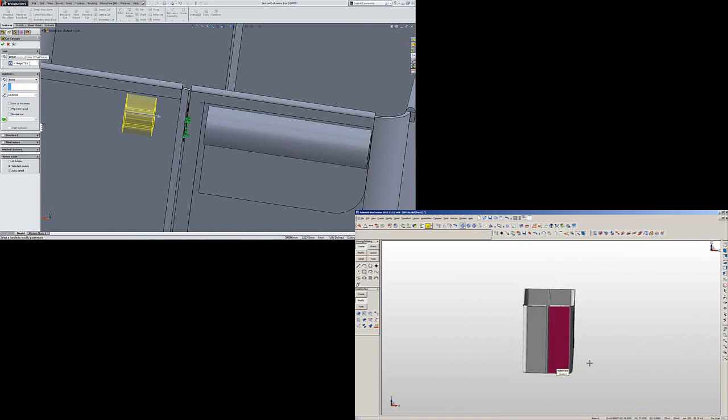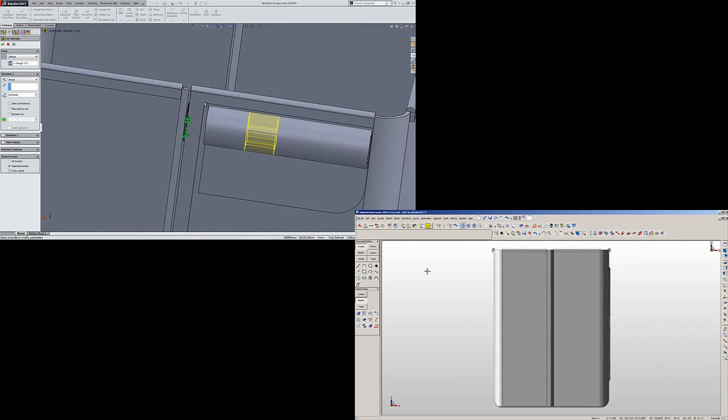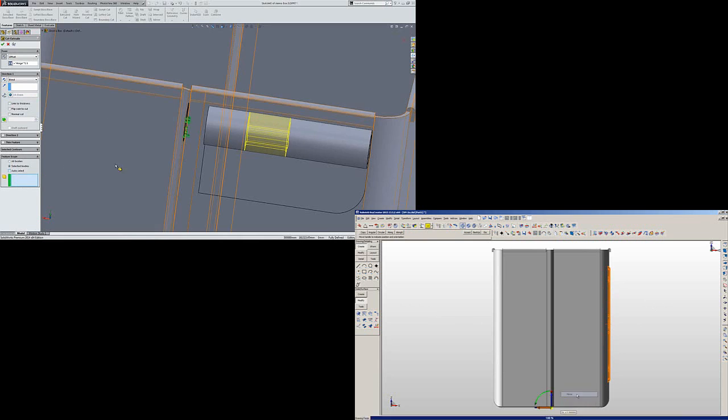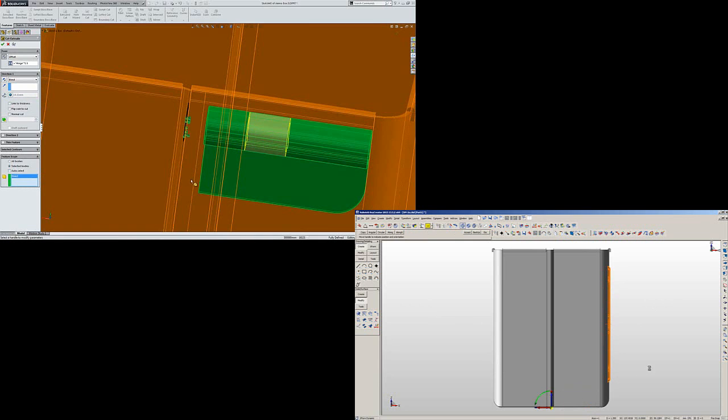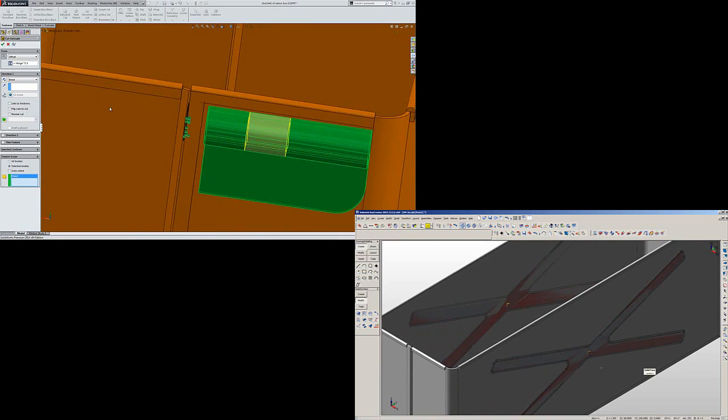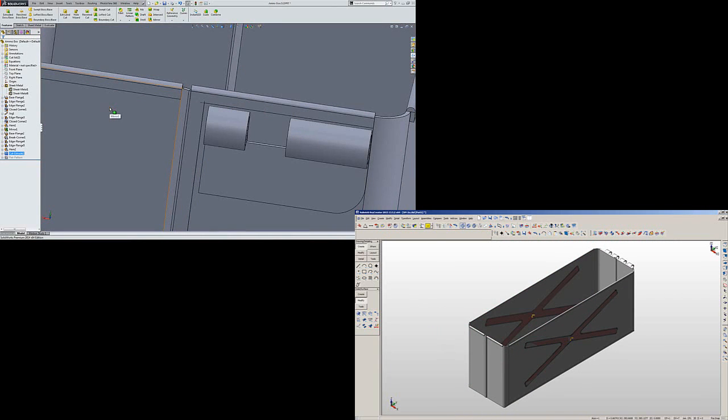Okay, and we'll just reverse that direction. So it's taking this hinge size and half of this, and it's just cutting it here. Now we just need to have a blind condition of the global variable hinge at 14.11, and for our selected bodies, our feature scope, we're going to have it on just this body here. And okay that.